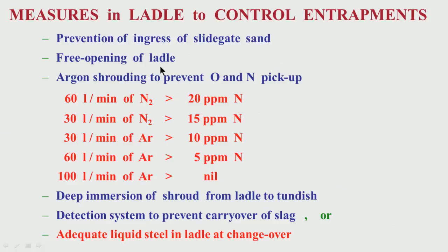Next, I have told free opening of ladle. Ladle should open free, that means when you open the slide gate, the liquid steel should come down from the slide gate exit. So, this is called free opening. There should not be any oxygen poking.